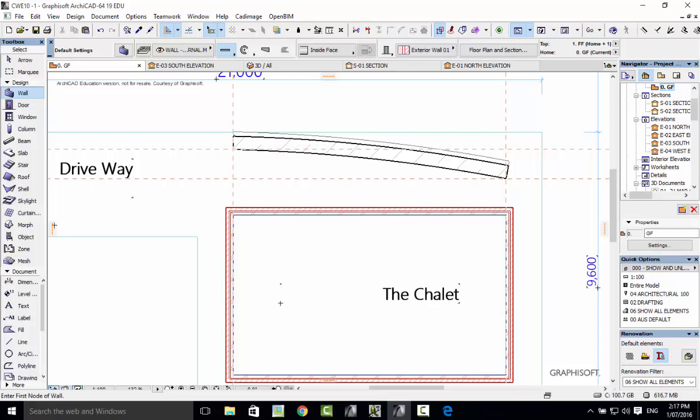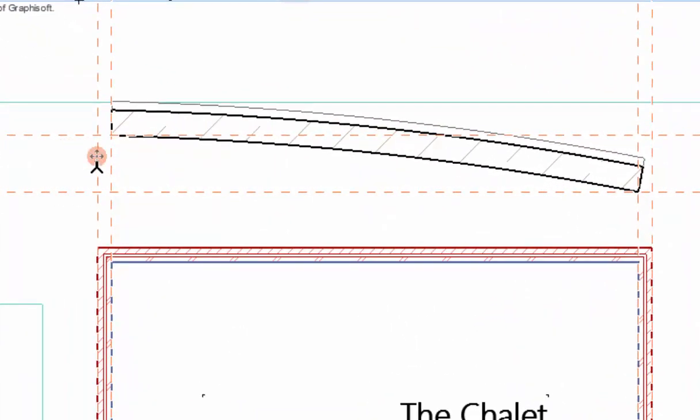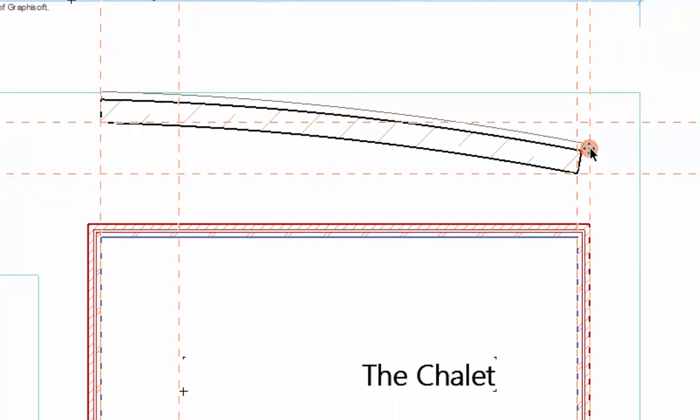Let's put our reference lines in. Let's bring that, snap it to the outside, and we'll bring one from this side. Snap it to the outside. Now when we grab the orange circle, there it is, just drag it in and then type 1800, enter. And the same on this side. Make sure you select the right one, the outside. Just drag it in, 1800, just type it straight in, enter. And now we have our position where we're going to draw our walls in.